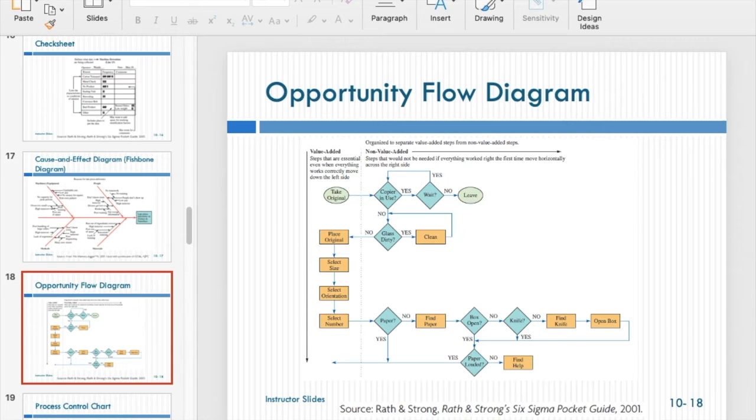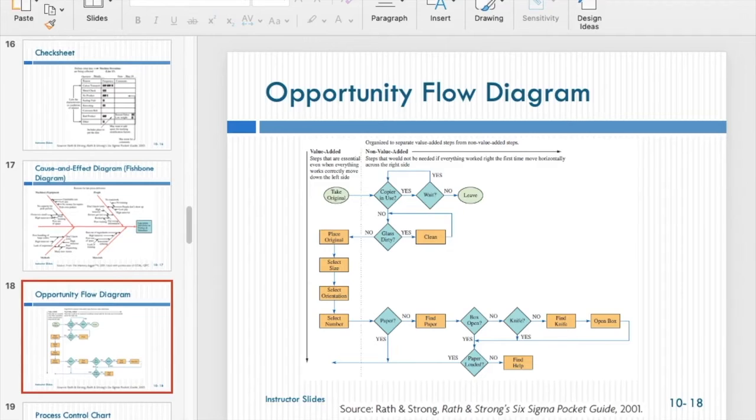But normally when we use the operation flow diagram, we will use, let's say, the check sheet or the cause and effect diagram simultaneously, because the operation flow diagram itself gives you the sequential procedure. If you use it with the cause and effect diagram or check sheet, that will help you, because the underlying reason for using all the different diagrams is to help you explore the underlying reasons of the defective products. So sometimes we use some of those diagrams simultaneously.